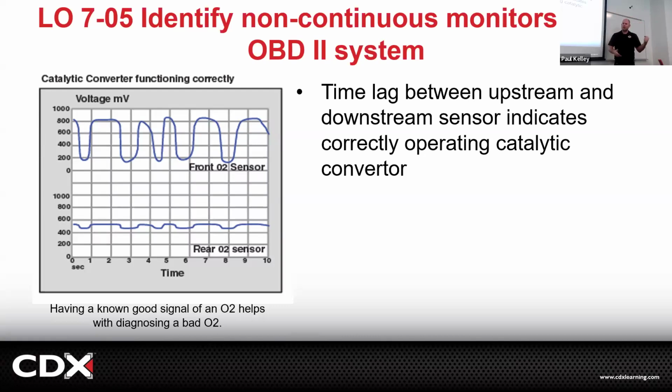Now, if I pull the vacuum line off and the sensor doesn't really respond right, I'm going to be like, what is up with this sensor? Hello, I just added a bunch of air. Why aren't you responding, right? So you might even say, interrogate the suspect. Well, if you're getting closer, though, wouldn't they start adding more fuel? Not right away. So the sensor itself is going to flatline mostly, right? At least for a bit. And then, yes, it should start to add fuel and it should pull it more towards center.